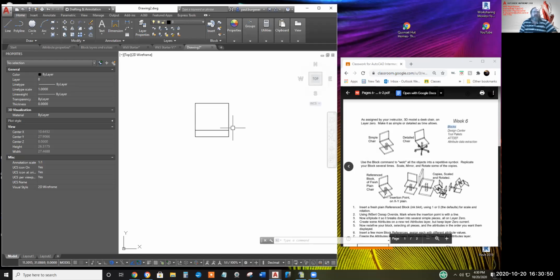By using blocks, or I think the official name is block references, it takes up a lot less storage space for your CAD file, because the definition of the rubber stamp or the block is placed in one spot in your CAD file, and then for each repetition of it, the only information it says is, hey, this is a block previously defined in the block table of this drawing.